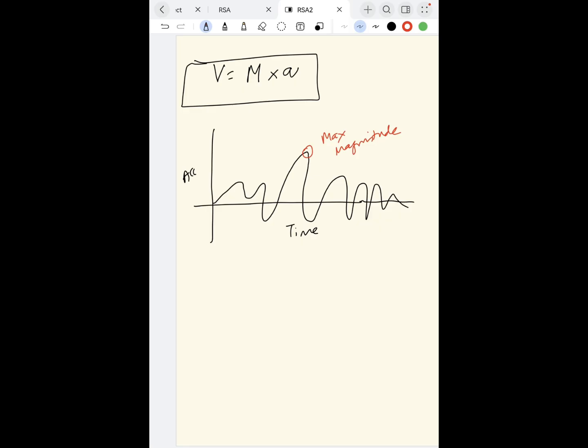For a single degree of freedom structure, the maximum response of the structure due to the earthquake depends upon the natural time period. For demonstrating this effect, let us consider a normal frame building with 0.2 seconds of time period, exerting an earthquake force of E1, and measuring its acceleration, and creating a graph like this.